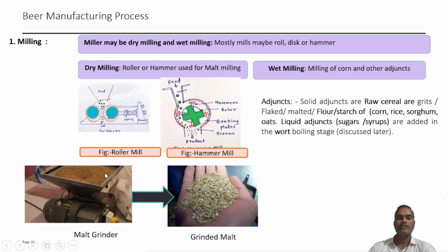The basic purpose is that the cereal grain contains soluble constituents which are properly extracted during the mashing process, and the natural enzymes present in the grain must be retained and stable during the processing temperature and pressure conditions.